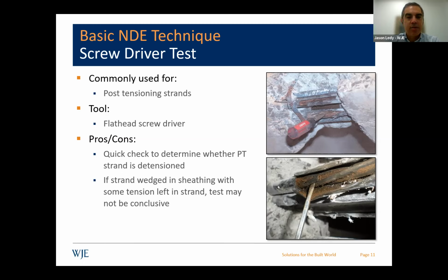However, the wires tend to loosen up if the strand is relaxed. So it's a sort of quick, low-tech way to determine if the PT strand is tensioned or detensioned. One of the potential complications with this test is if the strand is detensioned and it is somewhat wedged along the sheathing in some other locations, or partially detensioned, it may not be entirely conclusive.